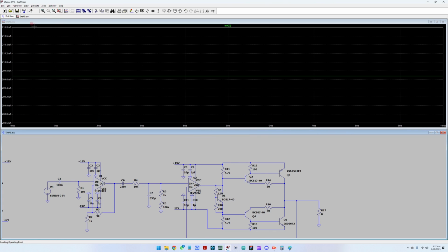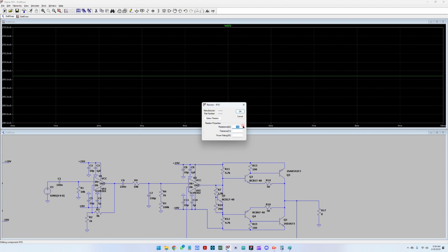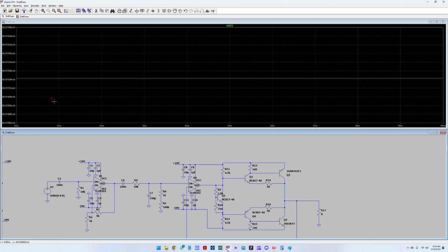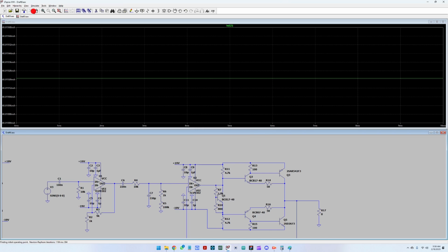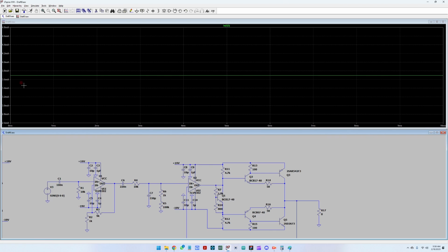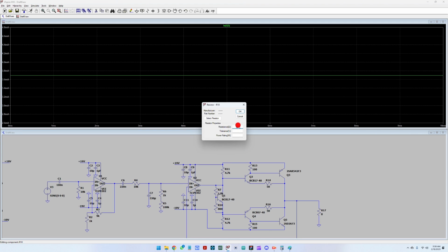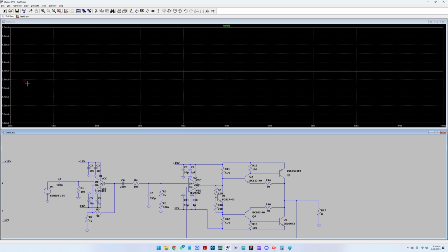Let's see, oh, too much, 200 milliamps. 750 ohms. Let's see, 40, it's still high. Yeah, let's leave 800, and for 800 it's 3.8 milliamps. Probably it's going to be like 790 ohms. Yeah, let's see if this is a bit higher.